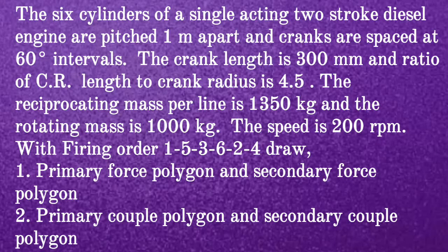The reciprocating mass per line is 1350 kg and the rotating mass is 1000 kg. The speed is 200 rpm. With firing order 153624, draw first primary force polygon and secondary force polygon, second primary couple polygon and secondary couple polygon.